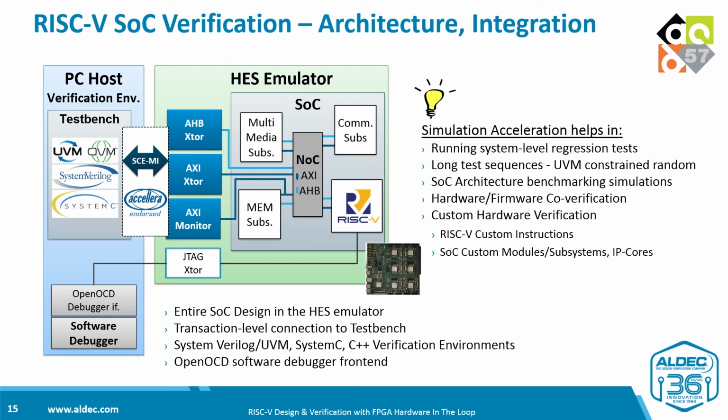A SystemVerilog, UVM or SystemC test bench connected with the SoC design through SCE-MI transactors enables deterministic test runs. In case of test failure, it can be debugged directly in emulation, or the failing test can be repeated in a pure simulation environment.